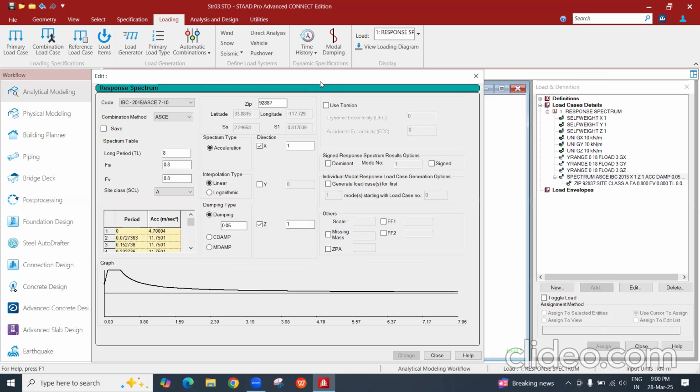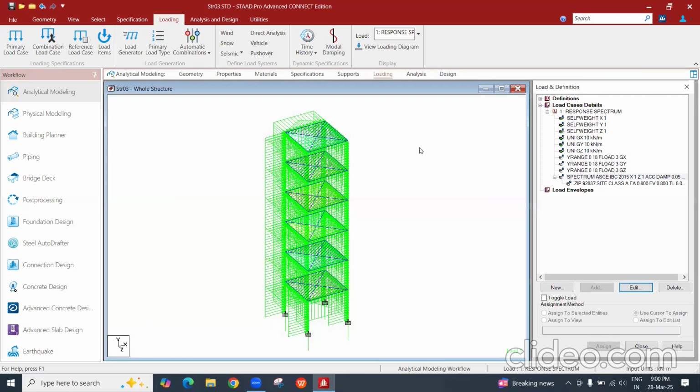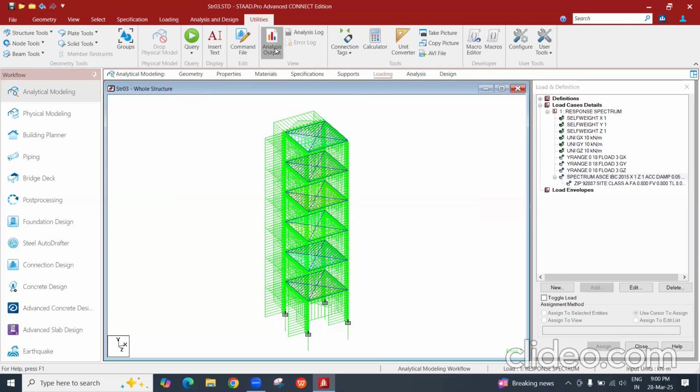Yeah. So once we change the things here, and see here also the site and all is there, because of that maybe there is that much difference. Now you need to consider: if it is a simple small structure, static analysis and those results are enough. If it is a complex and huge structure, then this kind of response spectra output also you can consider as the basis.